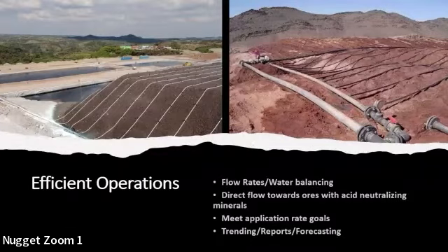In addition, the flex wall provides a more consistent compression around the entire column, so you have more uniform consolidation within that cell, versus just a one-dimensional uniaxial compression vertically from the top. So that's the benefit of the flex wall cell. I'll show some pictures coming up of what that looks like.